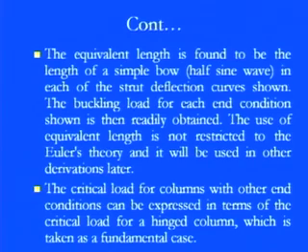The buckling load for each end condition is therefore readily obtained. If both the pin ends are there, then in one case it is simply pi square EI over L square. In the second case, where the full sine wave curve is there, with two peaks, obviously it is 4 times, and if we go to the third mode, then it is 9 times pi square EI over L square. So all these solutions under the buckling load are readily available.